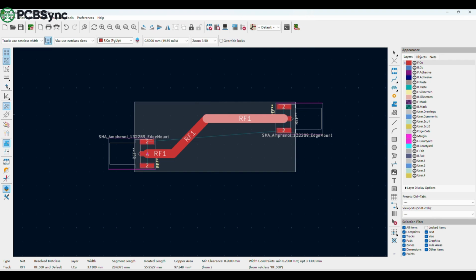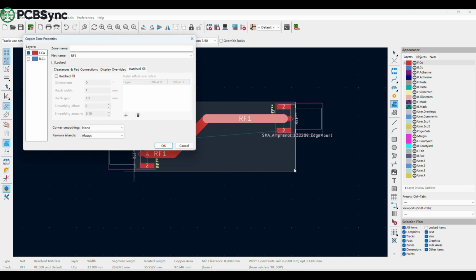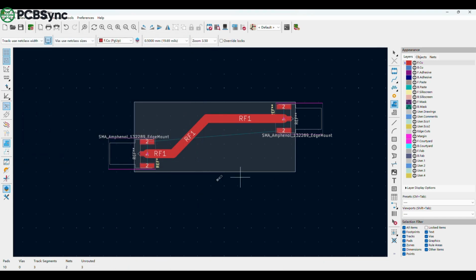A lot of beginners just focus on drawing traces. But what you really need to pay attention to is that there should be a complete reference plane underneath the entire RF trace, so we still need to draw one, a ground plane, and assign it to a certain layer. We need to choose the bottom layer. Then, set the net to GND, then click Confirm. And that's it for this part.